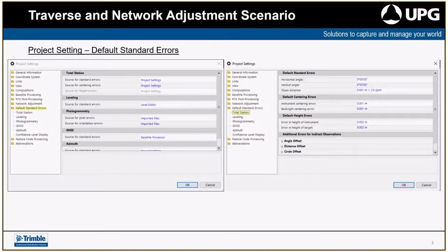I can tweak the angular distances, the horizontal and vertical angles, to suit what I want to see, which I might get through in the weighting side of it later on. It's horses for courses. Some people like to have it set by instrument. I like to do it with project. I like a little bit more control over it instead of what might be preset by somebody else.